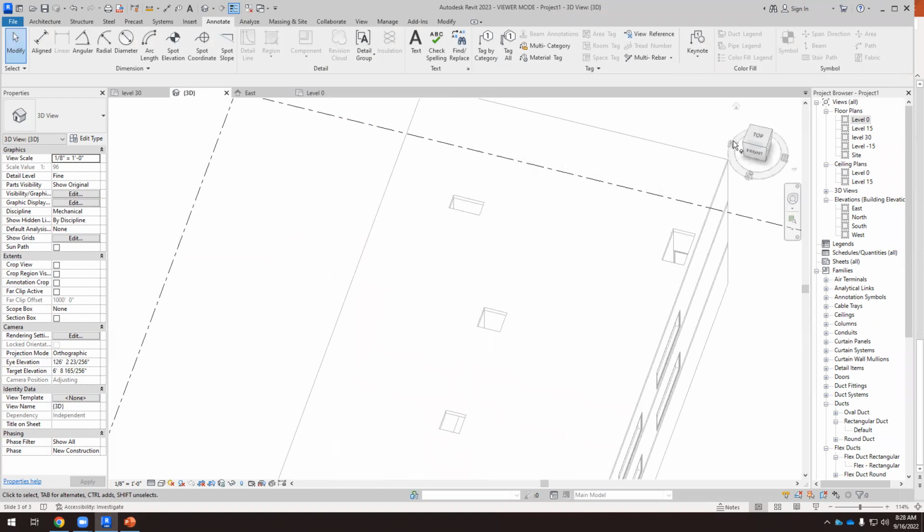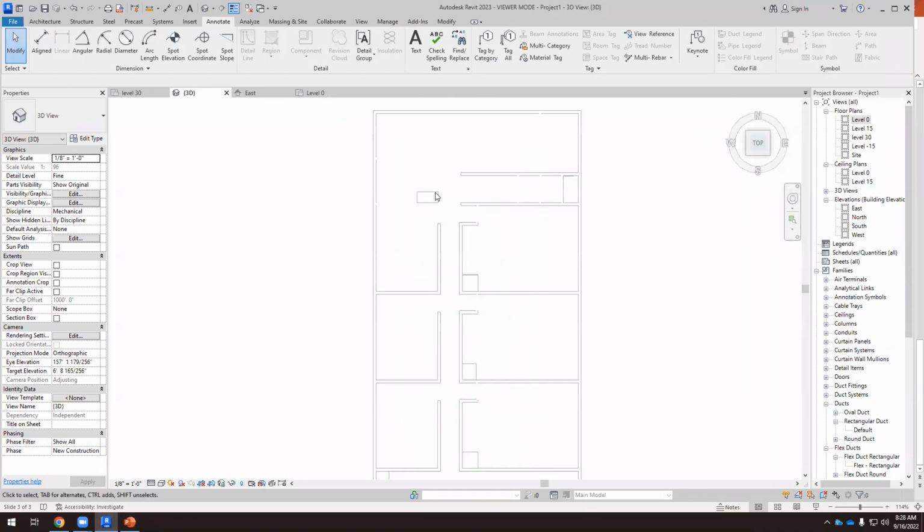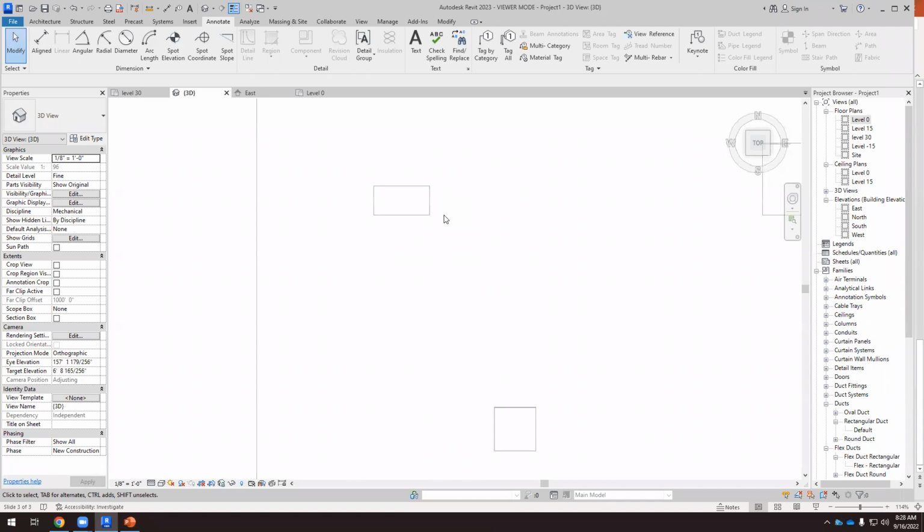So if this is the shaft we are going to use, now the air handling unit should be close to this one. If we place the air handling unit here, there will be a long duct from the air handling unit to that shaft. So first, we have to decide where we have this vertical element. And when we decide where the vertical element is, then the air handling unit should be close to that one. Okay, so this is the first decision that we have to make.